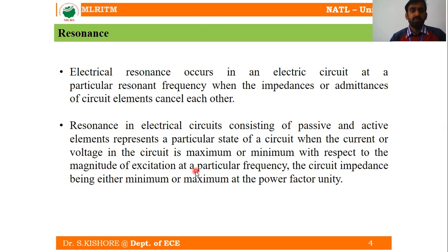It is the particular state of a circuit when the current or voltage in the circuit is maximum or minimum with respect to the magnitude of excitation. This is going to be applied by an external source at a particular frequency. At this frequency, the circuit impedance could be either minimum or maximum at unity power factor.